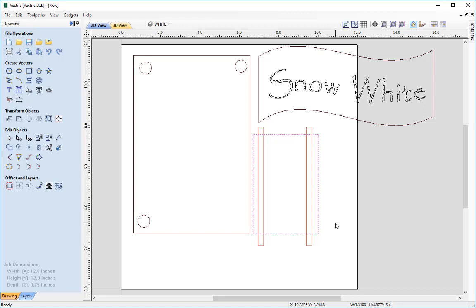And that can be where we run into trouble sometimes when we box select things, because in doing that we can actually select duplicate vectors, and we can select all vectors which we believe to be closed and they're actually open vectors, like we've just demonstrated here.